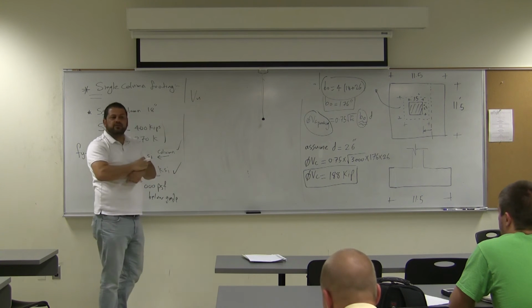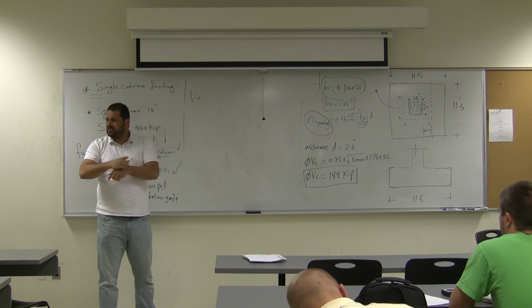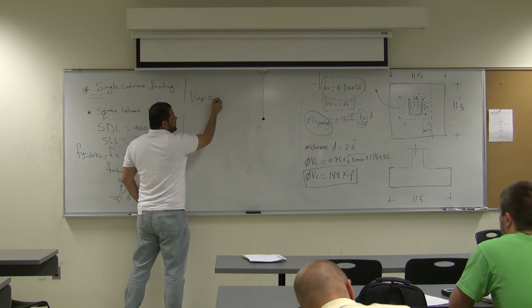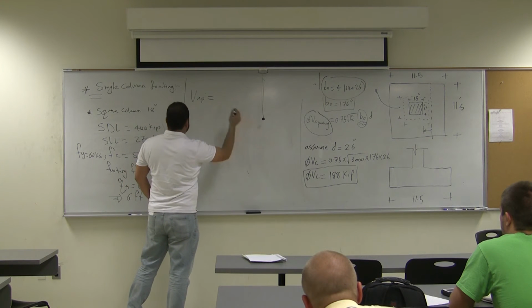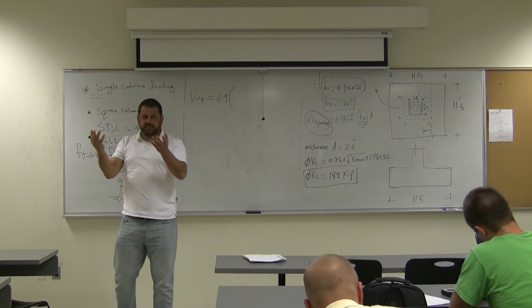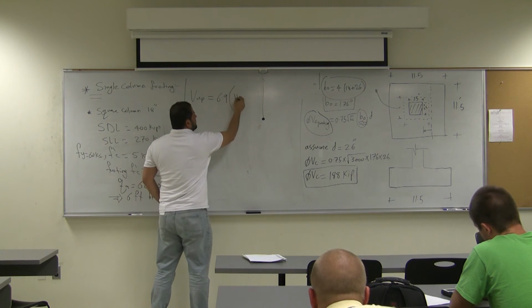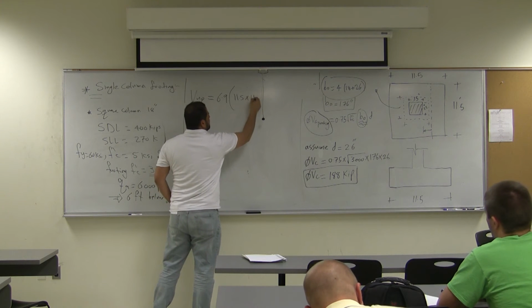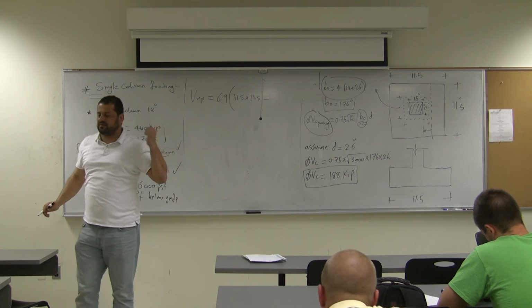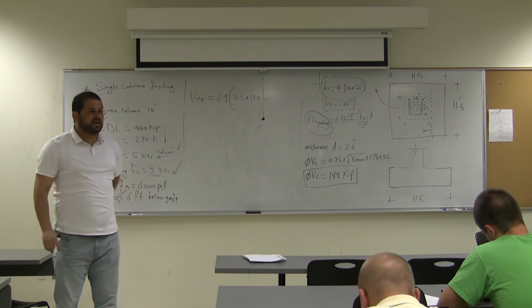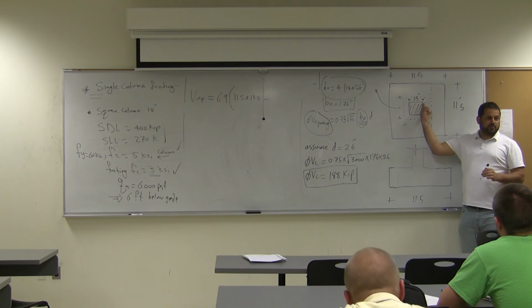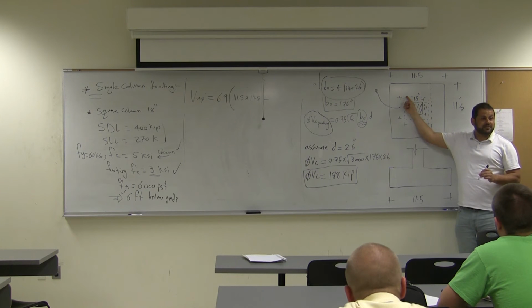VU, sometimes they call it VU2 or VU1, one for the beam shear, one for the punching. Just call it P, punching, equal Q ultimate, which is 6.9, times the area, which is 11.5 times 11.5 minus, now you tell me, what should I subtract? Is it 1.5 by 1.5? No, this area that will punch.